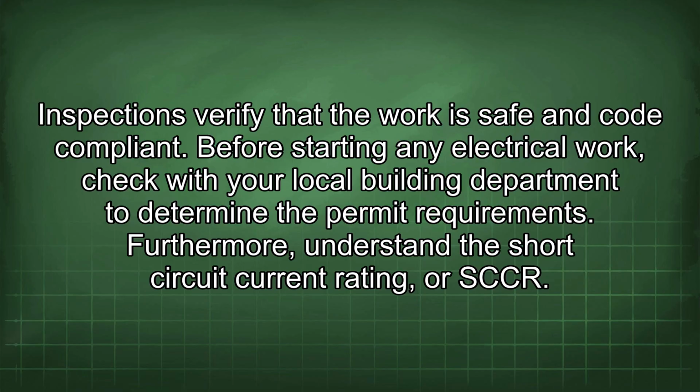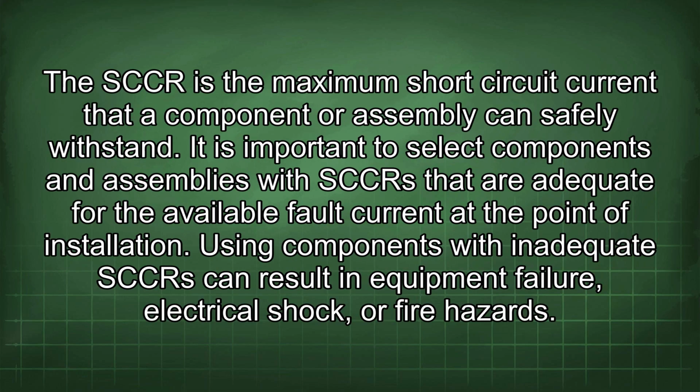Furthermore, understand the short circuit current rating, or SCCR. The SCCR is the maximum short circuit current that a component or assembly can safely withstand. It is important to select components and assemblies with SCCRs that are adequate for the available fault current at the point of installation. Using components with inadequate SCCRs can result in equipment failure, electrical shock, or fire hazards.